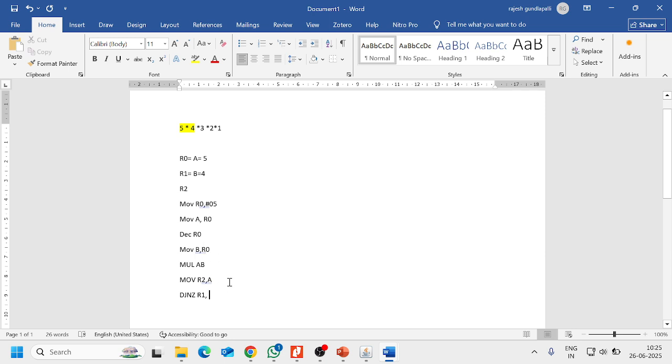you are moving that value. So one more small instruction we write, MOV R1 comma R0. So here I'll put it as R1 and here R1. So now it will be fine. Let us say it is a loop. Now where should this loop go? R1 value is 3, and this 3 has to be multiplied with the previous value. So here we'll put the loop.